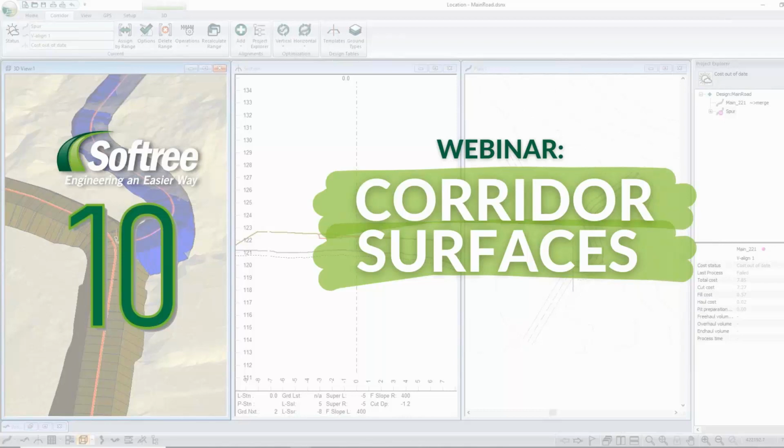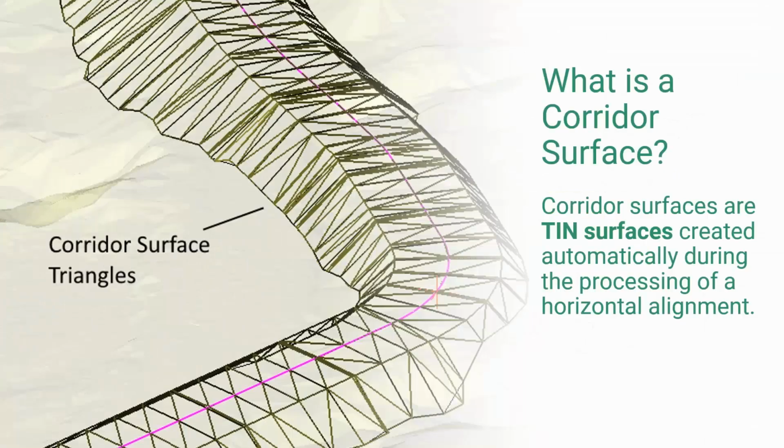So I'm going to start off here with a little bit of an introduction just to what corridor surfaces are and a little bit of the background, and then I'll pass it over to Craig for the first example. So corridor surfaces are basically TIN surfaces that are created automatically during the processing of a horizontal alignment. So you can see here in the picture, it's just a triangular irregular network that is being made from that road surface or alignment surface that you've created.